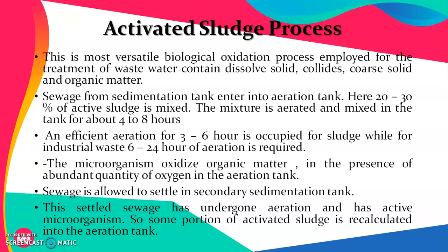So in the aeration tank we continuously add a very high amount of air to the mixture of wastewater and activated sludge. Then it is allowed to settle in a secondary sedimentation tank.